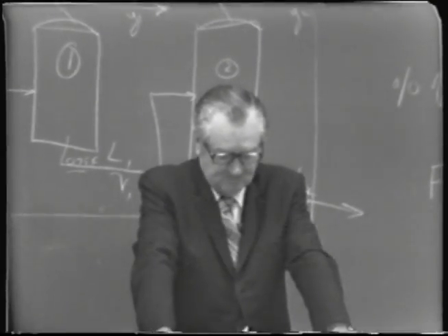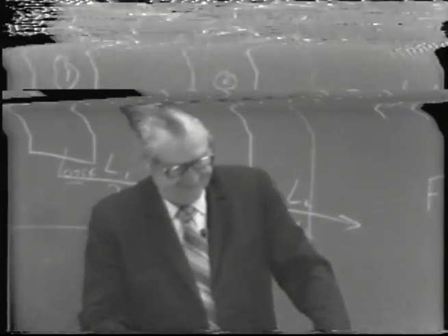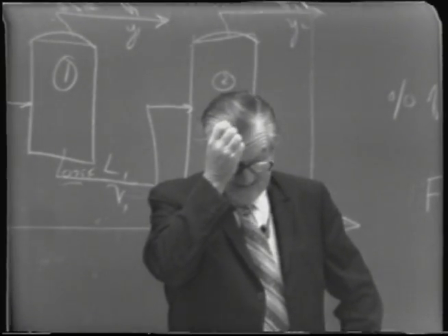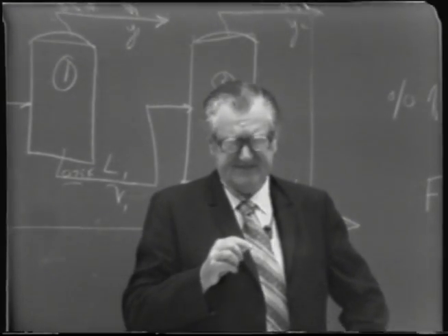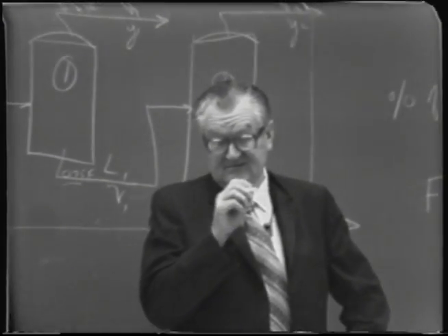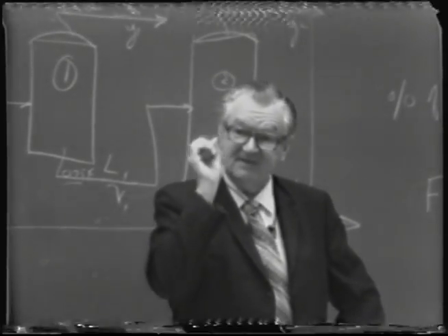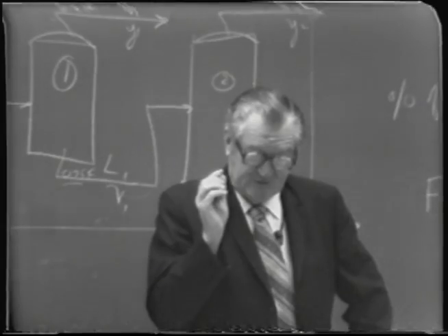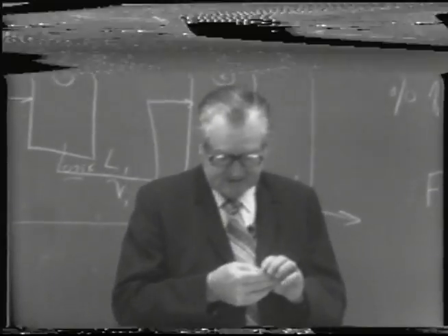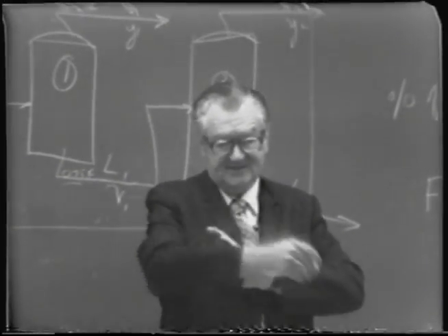I had qualitatively indicated how you can utilize the vapor-liquid equilibrium curve to visualize how you can go from one concentration to another by repeated steps, particularly if we consider the system under equilibrium, which in practice is only by taking the steps between the curve and the diagonal line.